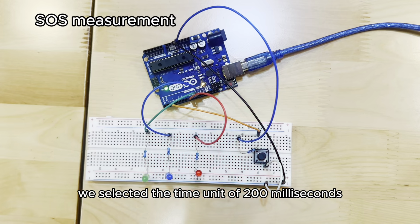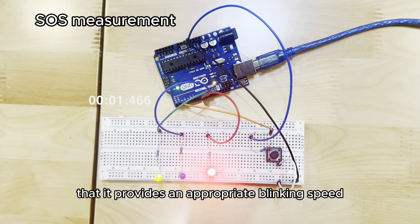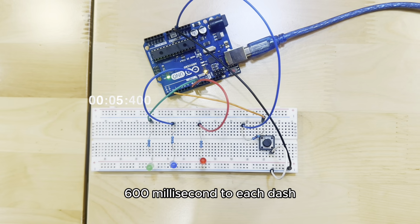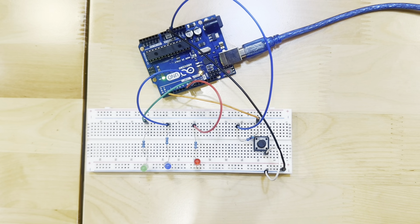We selected a time unit of 200 milliseconds based on our belief that it provides an appropriate blinking speed for the system. Consequently, we assign a duration of 200 milliseconds to each dot, 600 milliseconds to each dash, and 600 milliseconds to the gap between characters.